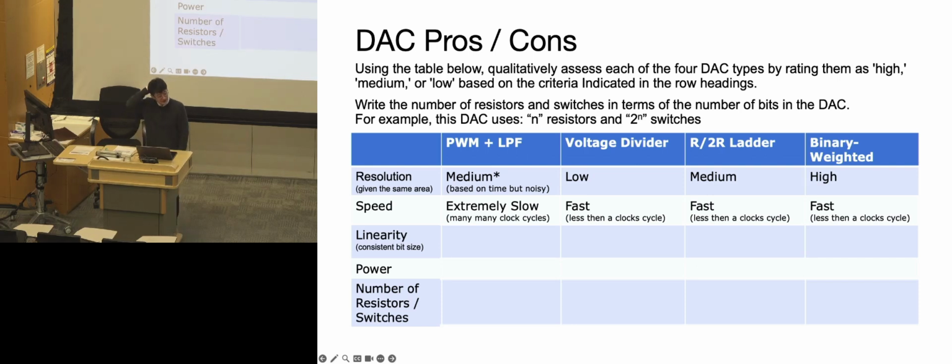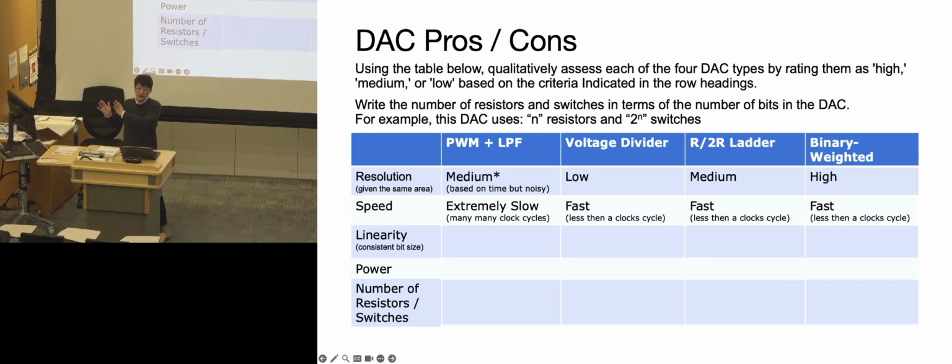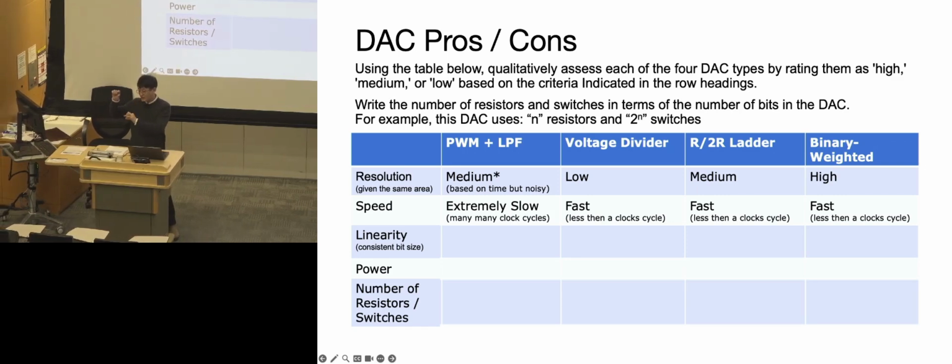In case I didn't explain it very clearly before: imagine we have a 4-bit DAC, then we have 16 steps. Basically, it's how close each of these step values on digital is to the actual analog output. On digital, if you increase from 0 to 1 versus from 14 to 15, the amount of value changed should be exactly the same on the analog output, right? But in reality, the changes in each of these two steps might be slightly different, depending on your DAC's configuration or hardware. So this is essentially asking how close each of these steps is within each of the digital values. Hope that clears up some confusion.